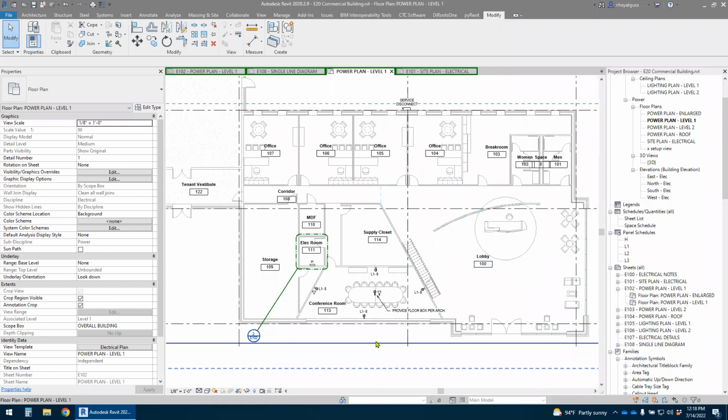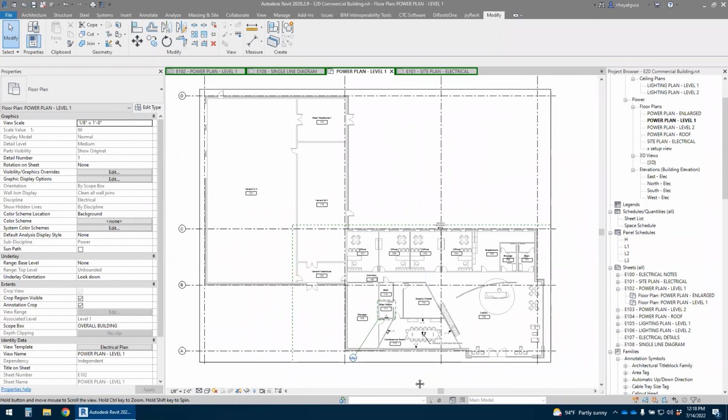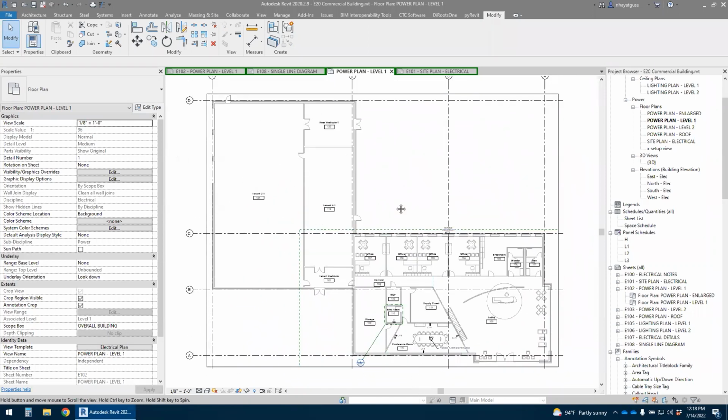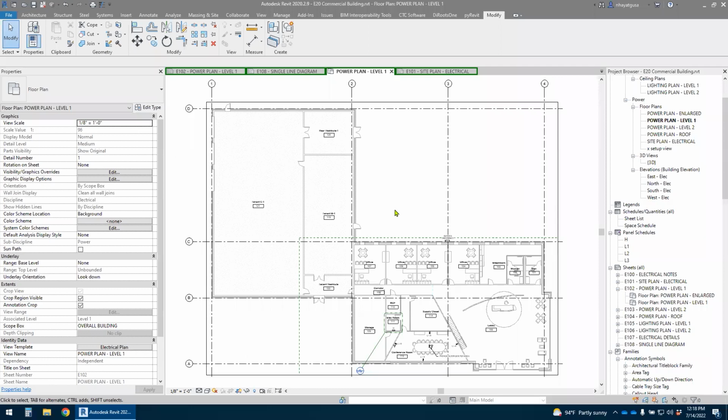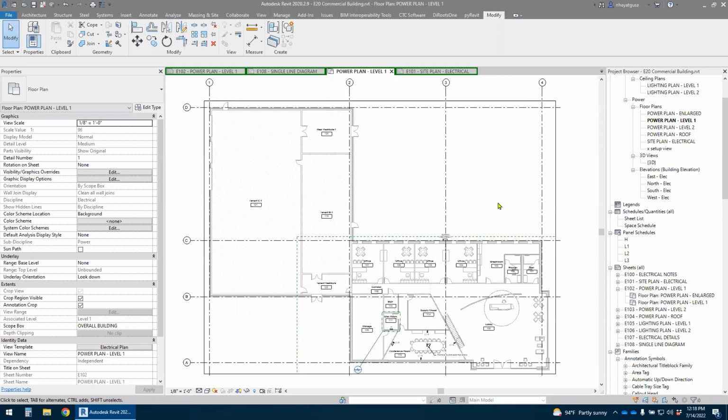All right, you've got your single line elsewhere. I'm eyeballing this and I'm seeing that it says the word space there. I'm just going to delete the word space. Okay, hit save. Revit does not auto save, right? So it will do reminders every 15, 20, 30 minutes: hey, save, hey, synchronize, but it's not going to do it for you. Their justification behind that is your files are enormous, or it's working on the cloud and you've got a slow connection, so they don't want to force you to auto save. I wish they gave us the option, but we are stuck with manual. There used to be an add-in for auto save, but they stopped updating it in 2018.